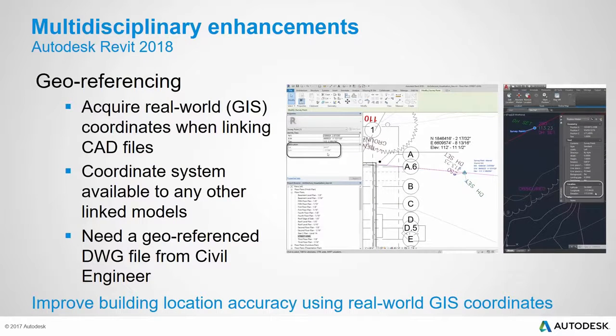This here was probably one of my favorite new features. In addition to the Navisworks models, the ability here to acquire coordinates from georeferenced drawing files. Most of us, when we're working with an architectural site model, and that's how you should be working, as an architectural site model, and then you link your architectural building into that site model and you publish coordinates to it.